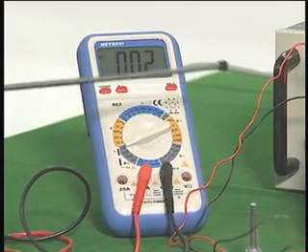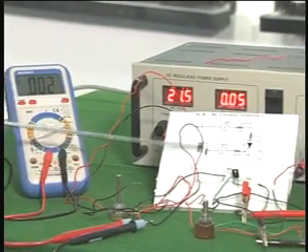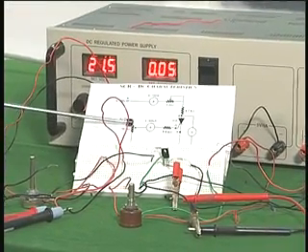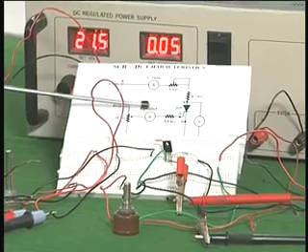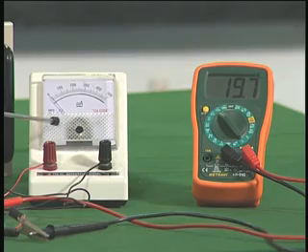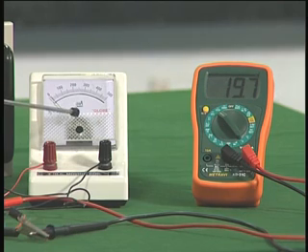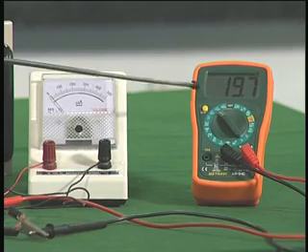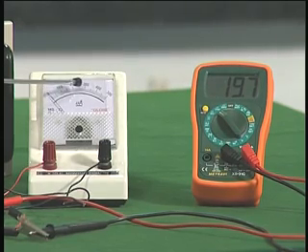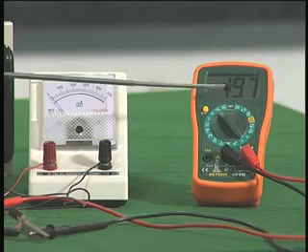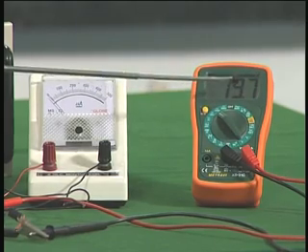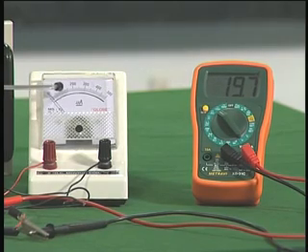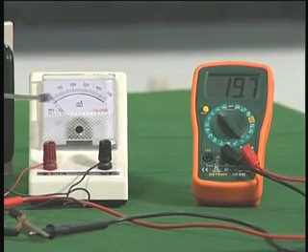So now what I am going to do is vary this position, so that I will apply larger and larger voltage. It is now in the minimum position. Now I will increase it so that there is a current. I want you to observe this microammeter for the gate current. You will observe this microammeter when I am changing. I have kept these two close together, so that when the current here becomes large, the voltage here will become less. That means the SCR has broken down, it has come into the conduction state, and therefore this voltage will become less than 1 volt. When this current reaches a critical value, this will happen. So I want you to observe these two.